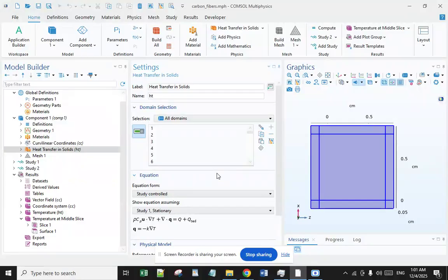Heat transfer from a layer of a carbon fiber cluster at low Reynolds number. The heat transfer coefficient from a cluster of very fine carbon fibers was measured by a transient test method. Air was heated by a heater composed of a cluster of 8 micrometer diameter carbon fibers. The input to the heater was an electric pulse, and the transient gas temperature was measured and compared with the numerical results with an assumed heat transfer coefficient.